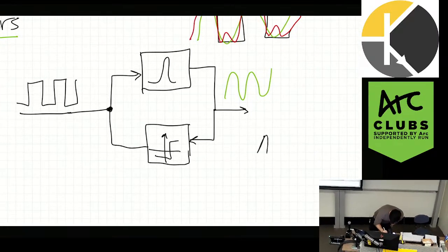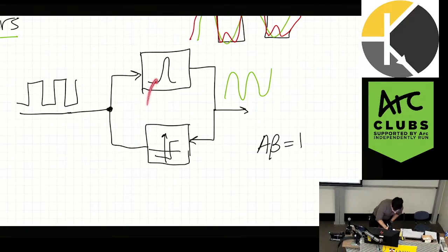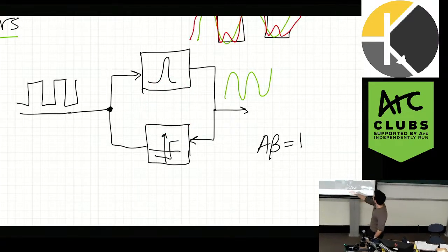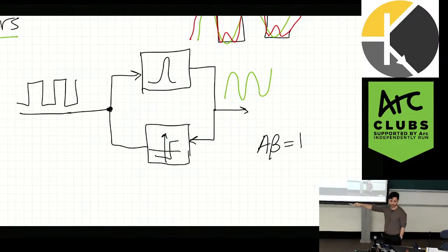But generally what we do is we start it, because we know for oscillators, the loop gain around the circuit has to be 1. Sometimes what we do is we start it up greater than 1. So we start up the oscillation. It's like you're starting a lawnmower. We start it really fast. And then once the lawnmower starts, we don't have to keep yanking it, because it's just going to work, right?